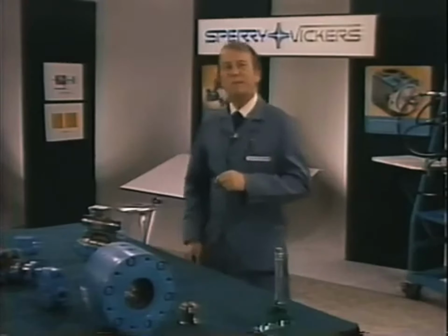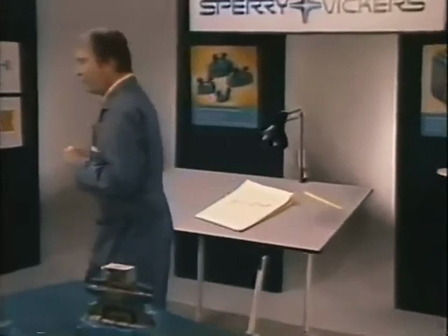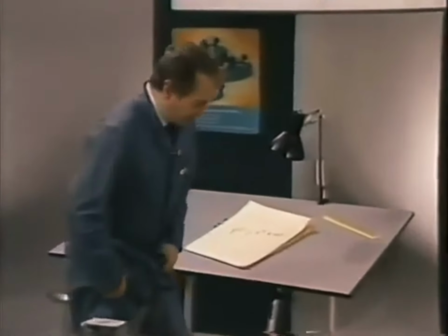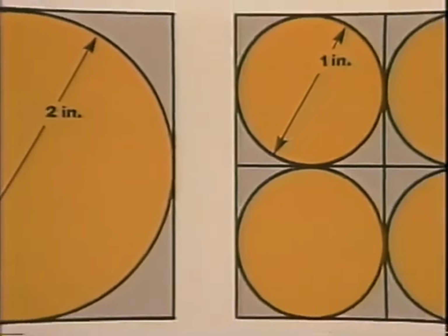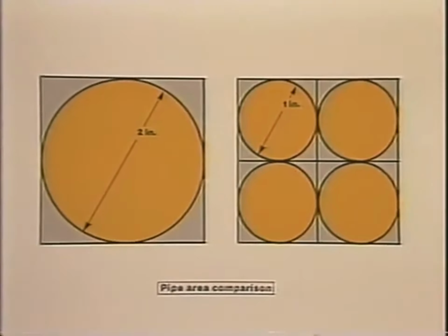By now, you're probably thinking that this hydraulic stuff is pretty simple, and you're right. Before you start out on your own, however, there are a few more things you should know. Oil is still the fluid most commonly used, but as slick as it is, it still takes some effort to push it through a line. I know that's the pump's job, but we want to make it as easy as possible. Did you know when you double the diameter of a pipe or tube, you increase the area 4 times? Perhaps it's more important to know that a tube with only half the diameter of the original one would have only 1/4 the area.